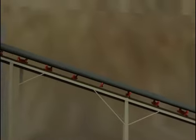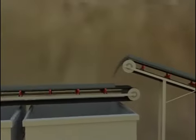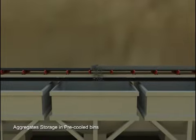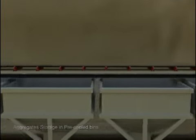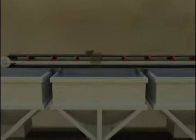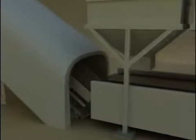Aggregates thus cooled are then carried via a closed conveyor and stored in pre-cooled storage bins. A strike plate mechanism installed over the conveyor directs the aggregates to fall in appropriate storage bins. Aggregates from pre-cooled storage bins are now carried via a closed conveyor to the batching plant weighing mechanism and further